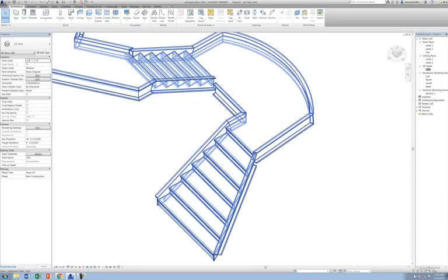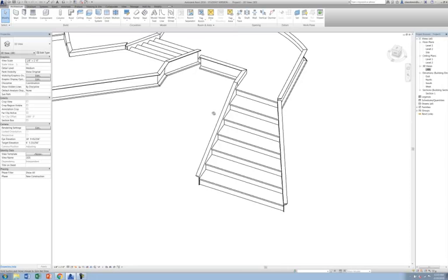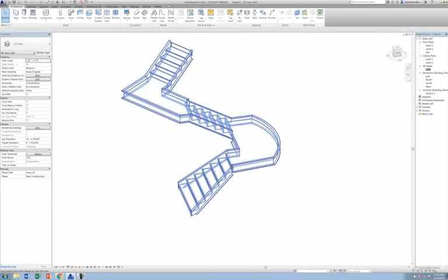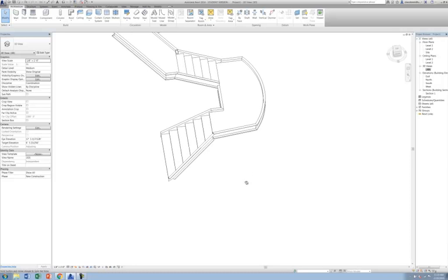Here, if you make a little straight run that continues the profile, you'll avoid these dirty connections. But for the most part, things are nice and consistent in the Revit staircase tool, and tend to make for pretty interesting kinds of geometry in pretty quick order.